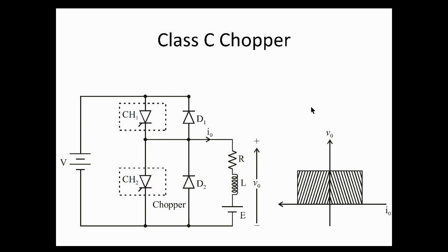Basically, you have a forward button and a reverse button. All right, good. You can use it there. So you basically have motor control and regenerative braking of the DC motor. All right. What kind of chopper would you say this is? Step up, step down, or both?